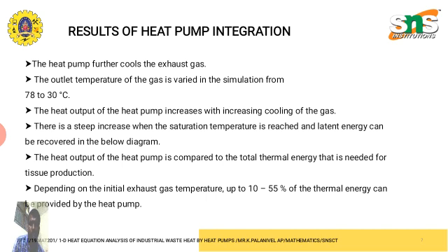Results of the heat pump integration. The heat pump further cools the exhaust gas. The outlet temperature of the gas is varied in the simulation from 78 to 30 degrees Celsius. The heat output of the heat pump increases with the increasing cooling of the gases.